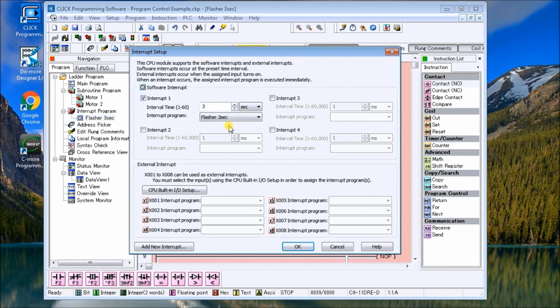And you'll notice that I don't have any of the programs themselves in the main menu. It's just by itself. If a timed event or an interrupt happens, here I can program my internal interrupts off of the built-in I/O and call up subroutines as they happen. So this happens outside the main program itself.